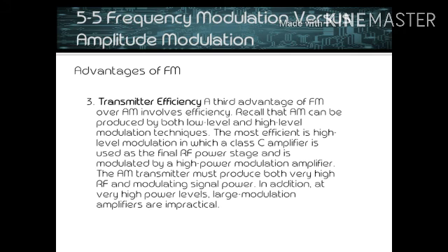The AM signal is generated at a lower level and then amplified with linear amplifiers to produce the final RF signal. Linear amplifiers are either Class A or Class B and are far less efficient than Class C amplifiers. FM signals have a constant amplitude, and it is therefore not necessary to use linear amplifiers to increase their power level. In fact, FM signals are always generated at a lower level, then amplified by a series of Class C amplifiers to increase their power. The result is greater use of available power because of the high level of efficiency of Class C amplifiers. Even more efficient Class D, E, or F amplifiers are also used in FM or PM equipment.